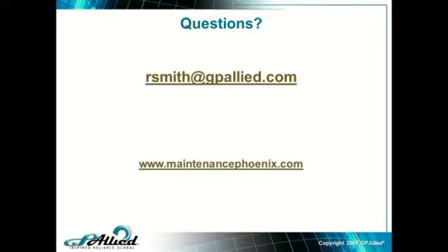Yeah, a lot of people ask me that question. In a few different organizations, we did some studies on it, and we saw only a little bit of difference by just assuming the equipment runs 24 hours a day, 7 days a week. Because it's the number of failures divided into time. So say it's 5 failures in a week, we divide that into 168 hours in a week. That's our mean time between failures. Now what if that equipment is down for 12 hours? What if it's down for 8 hours? You may find in the scheme of things, it's not critical. If it is, then you're going to have to measure it.